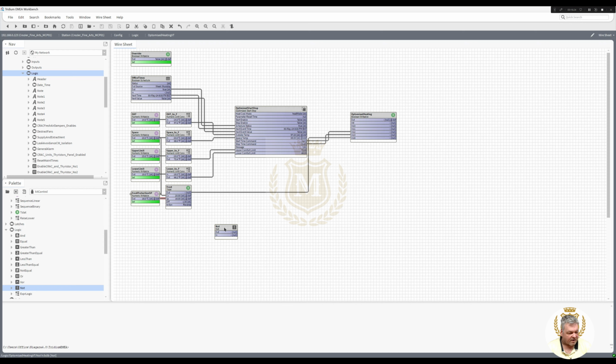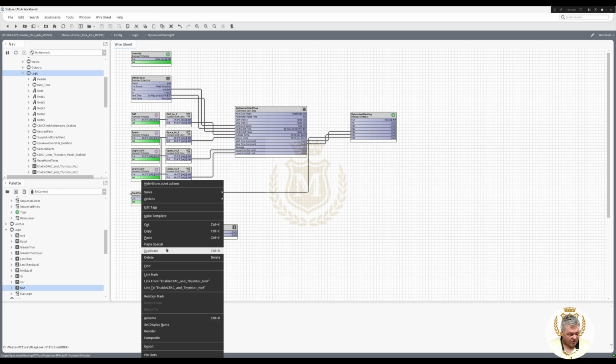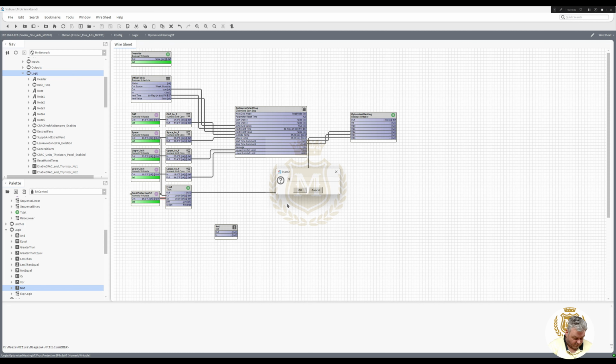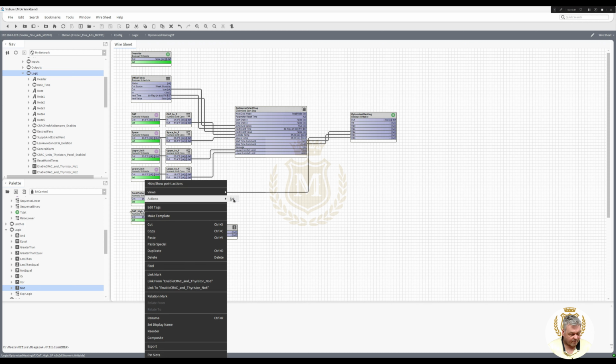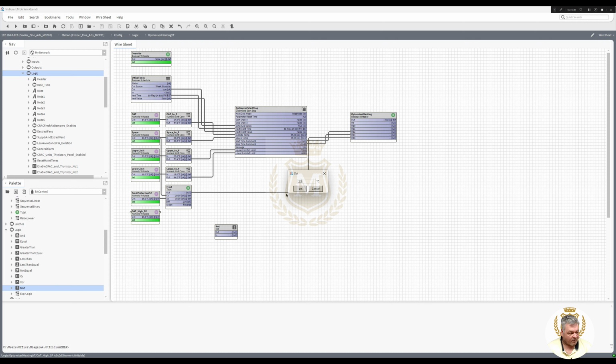I want to use the not gate for when it's outside air above a certain temperature. So outside air high set point. So say if outside air goes to 23 degrees or 22 or whatever, let's just duplicate that. OAT high. So whatever it happens when outside air gets high, we are stopping completely. Put that in the wrong place. We will stop completely the heating.